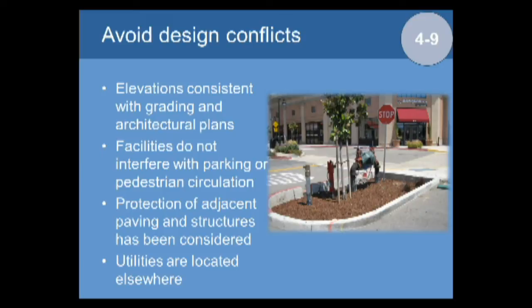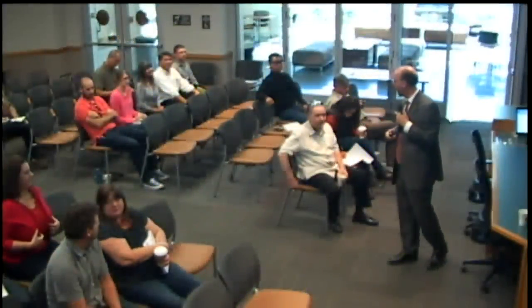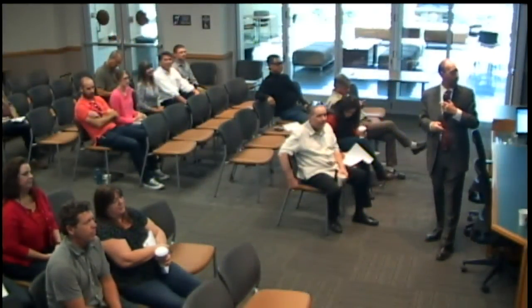And so here, obviously, after this was designed and sized and everything, it was decided to put in a backflow preventer. Undoubtedly, there's a pretty big foundation on that, a hydrant, another hydrant, and a stop sign. I think it's pretty much filled in what was going to be a bioretention facility there. So the lesson there is make sure that the utilities are going somewhere else. You often see the cable companies want to put their box in your bioretention facility. Not such a great idea.